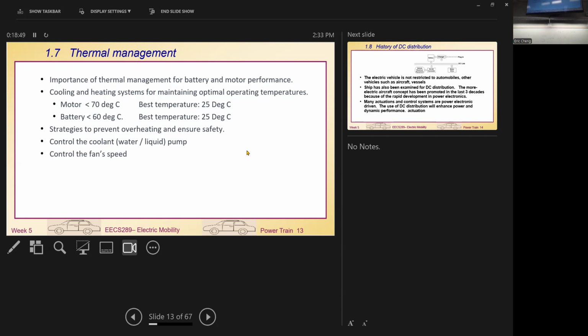The motors are using copper winding. In theory, copper winding is able to stand high temperature, but that's not the case. All the copper winding has a coating, an enamel coating, which is the isolation. That coating will break down at high temperature. Typically it will be something like 125 degrees for some coatings, and you can choose some coating even for 200 degrees C if you like. But basically, for most motor winding, the low cost ones, it will be close to 120 to 150. But that's only for copper winding.